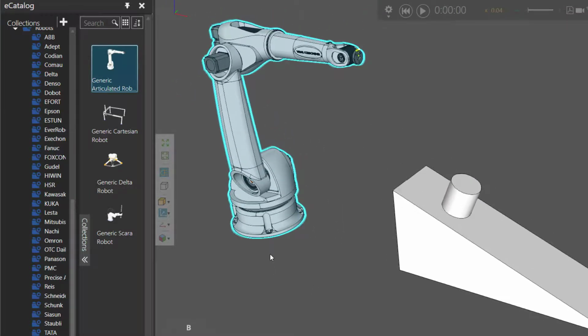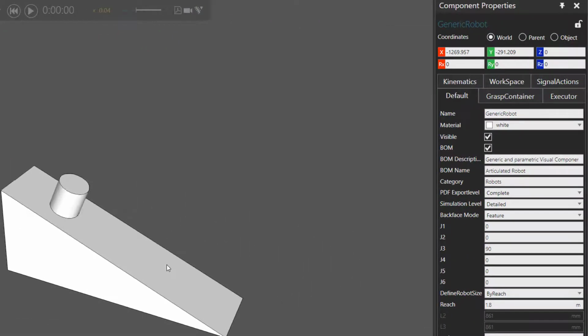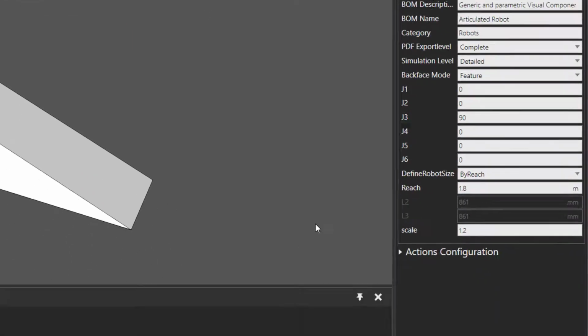And from here, we can program the robot to sweep the geometry of this cylinder. And what that means is that every iteration or step of a process will make a copy of the cylinder's geometry as it's moving. So if you have a broom and you start sweeping the floor, that's what we're talking about here. It's making a visual imprint of the geometry.